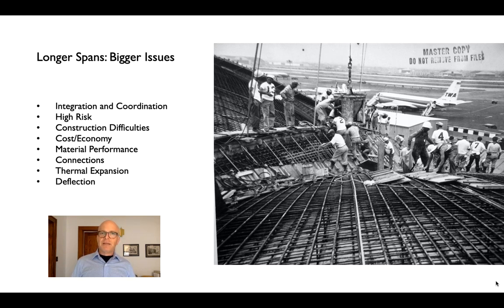And then two that we often don't think about but really need to, we're talking about big spans, materials that, like all materials, expand and contract in heat and that deflect under load. So when we're designing long spans, we're designing for static performance, but what we really end up with are almost kind of live animals, right? Structures that are growing and shrinking on hot and cold days, structures that are moving under wind forces maybe more than we would expect, and structures that are subject to, in concrete in particular, things like creep, right?